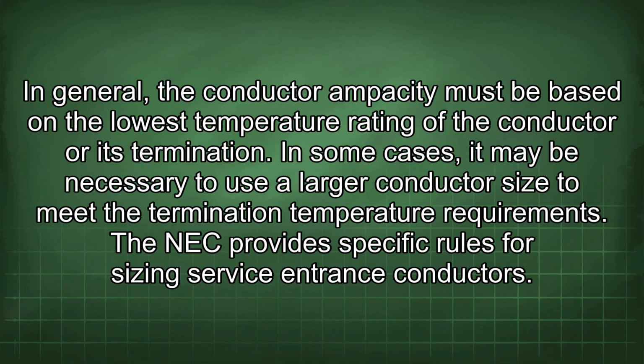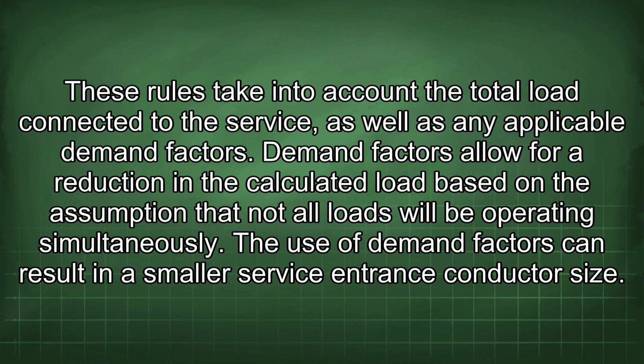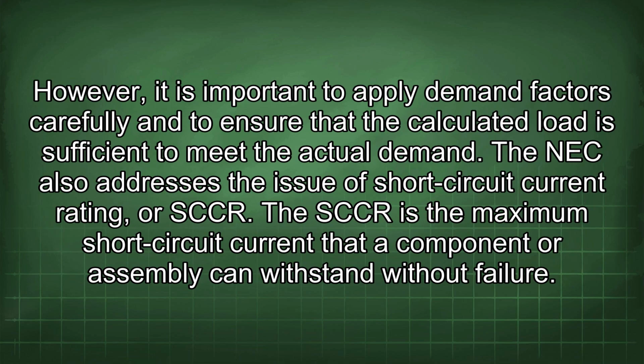The NEC provides specific rules for sizing service entrance conductors. These rules take into account the total load connected to the service, as well as any applicable demand factors. Demand factors allow for a reduction in the calculated load based on the assumption that not all loads will be operating simultaneously. The use of demand factors can result in a smaller service entrance conductor size. However, it is important to apply demand factors carefully and to ensure that the calculated load is sufficient to meet the actual demand.